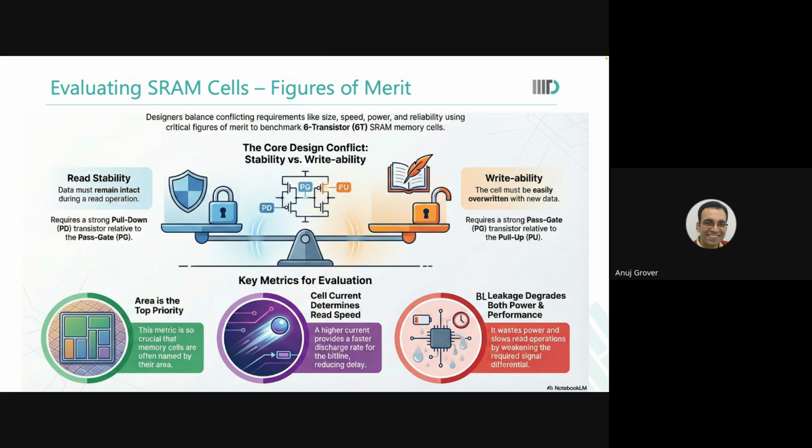See, one very important thing that you need to understand is that in most cases, performance and power are very closely linked. You want to improve performance, you have to improve power also. In most cases, unless you're talking about leakage, dynamic power and performance are very closely linked. Are you with me on this? Any questions until here?